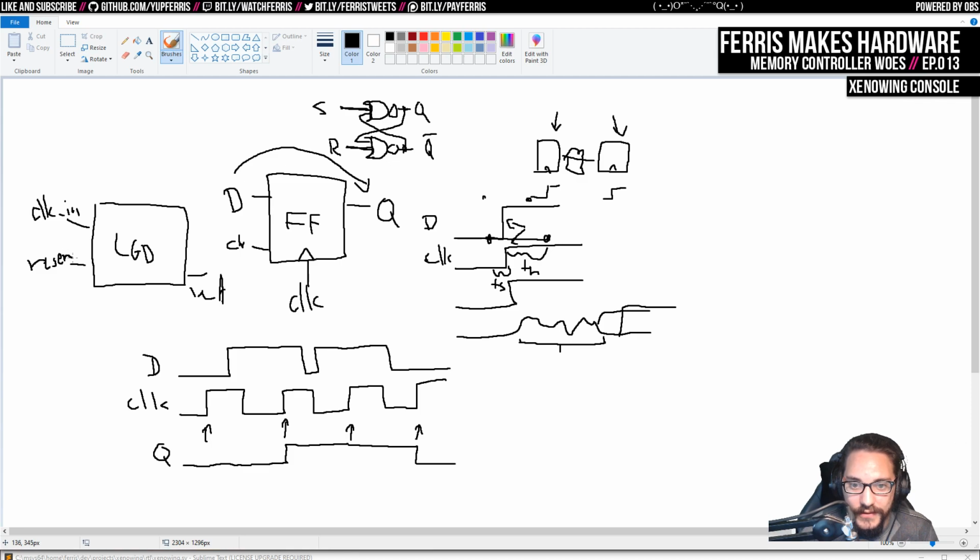And what I've basically told the tools is to not even consider the reset stuff, and I'll get to how I'm getting around that. That way it will ignore that in the analysis and just lay out the design based on the actual needs of the design, because this is going to be an asynchronous signal anyway. But that doesn't actually solve our problem. That just allows the tool to ignore the timing of that signal because it can't know it anyway.